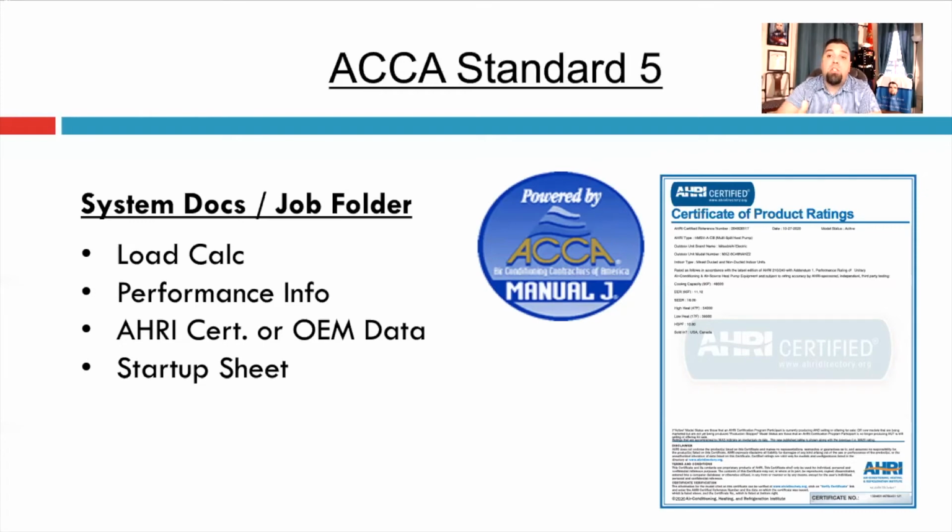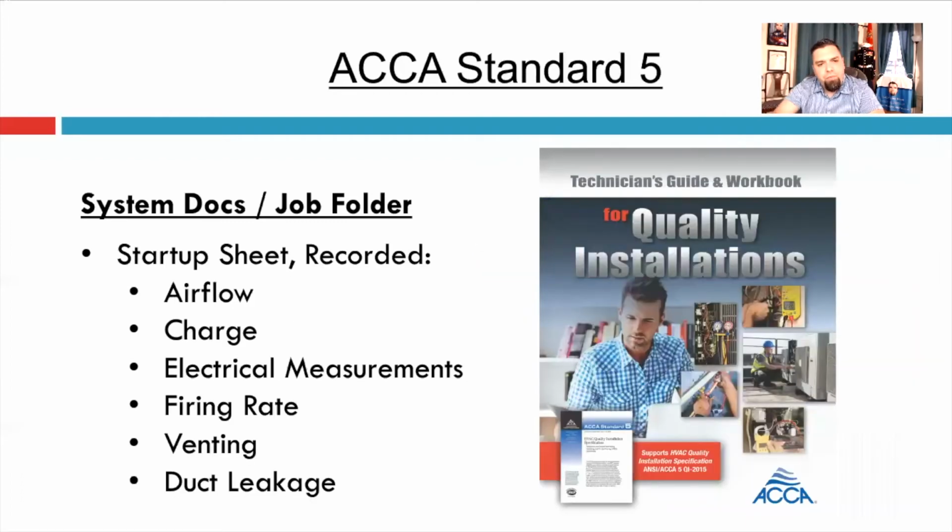And then of course the startup sheet that has all of the documentation I just talked about regarding airflow, refrigerant charge, electrical measurements, duct leakage, balancing, all that stuff needs to be put on that startup sheet. Pretty cut and dry there, all right? If you don't have this information, part of the technician's guide and workbook, which I'll give you just a little detail at the very end here, has these sort of sheets laid out for you.